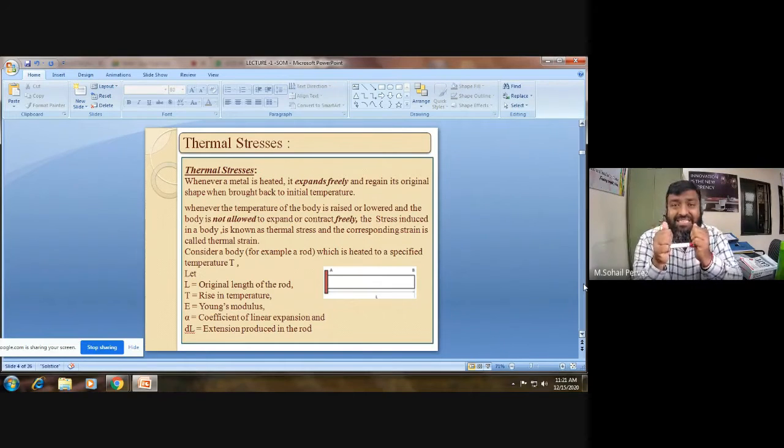So in this case, again the same definition of stress. I'm asking as question number two, whether this rod will be subjected to some stress, and in case number one, whether this rod was subjected to some stress. Now the answer would be very clear. Since in the first case, this rod was heated and no resistance was offered to its deformation or elongation, we can surely say in this first case there would be no thermal stress acting on this rod.